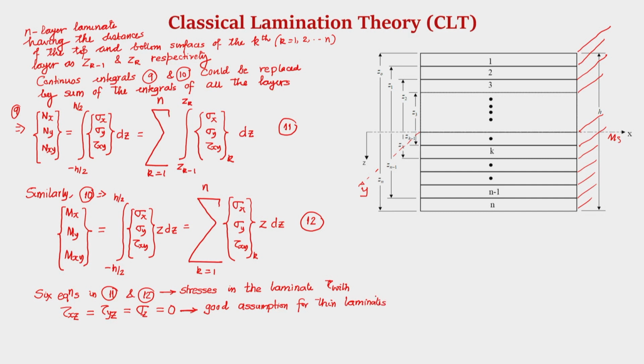Now that the stresses are actually represented by the force and moment resultant, let us apply the stress strain relationship. Now that we have obtained the statically equivalent system, where the stresses in each layer are represented combinedly by force and moment resultants, let us apply the stress strain relationship.